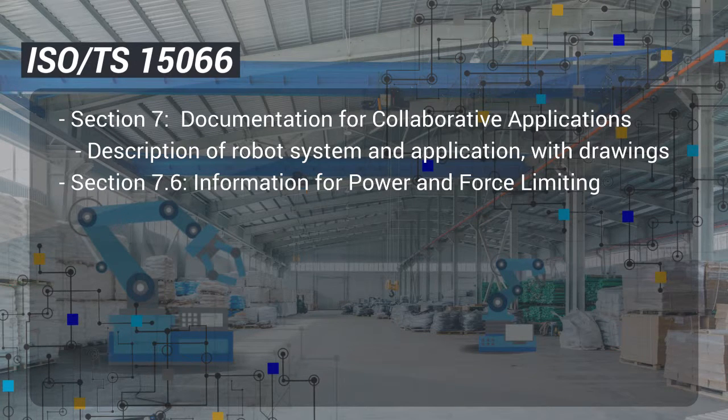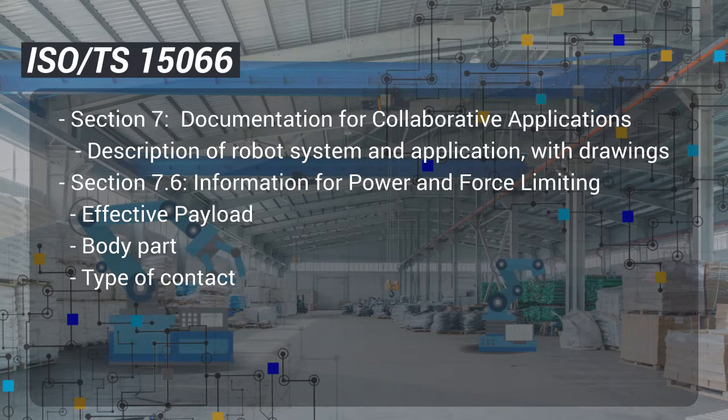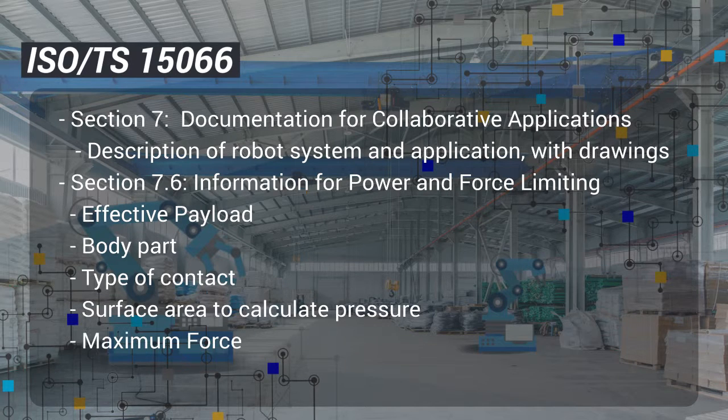For robots that fall under the category of power and force limiting, additional documentation is recommended. This includes the effective payload, which includes the robot moving mass, the end effector mass, the payload, and the forward reflected inertia of the drivetrain, which can be quite large. It also includes the body part that could be contacted and the type of contact that might take place. Contact could be free space contact or a rigid surface collision. As we demonstrated with our needle example, not only force, but pressure must be examined for these different types of contact.